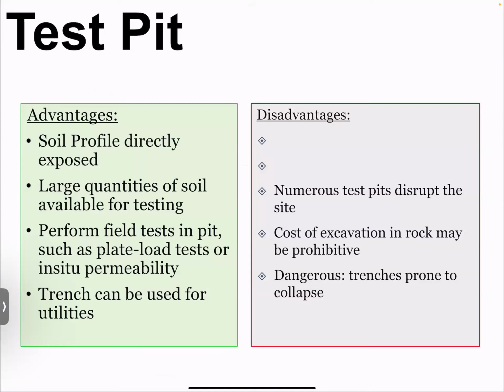The disadvantages are obvious: limited with depth. And then it's also limited with the groundwater table. So if you have a very shallow groundwater table, or if you're in a swamp, you can't be digging a test pit. So I shared test pits because this is an option and it is used in Florida. We're kind of starting from most basic, and then we're going to be getting more sophisticated as we go on. So think of it that way.